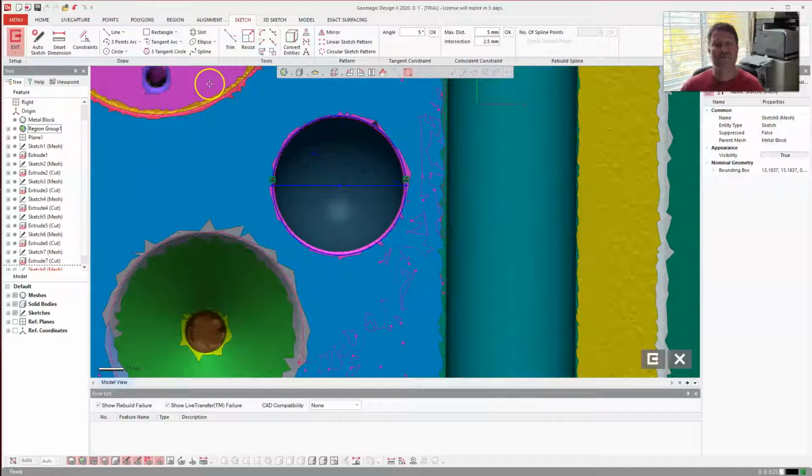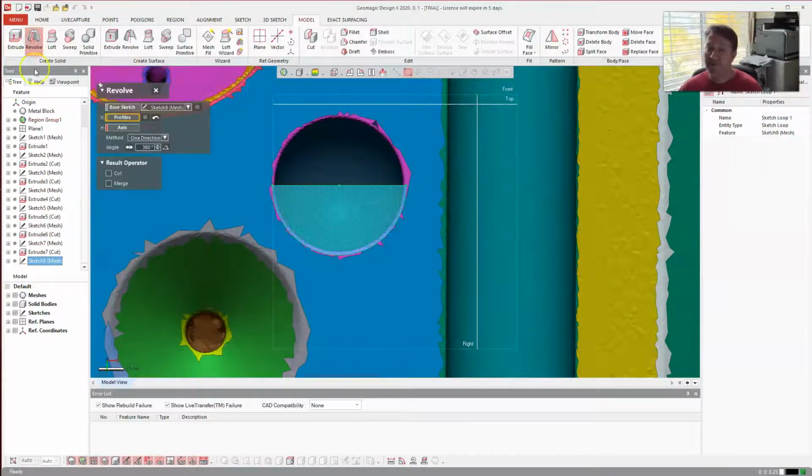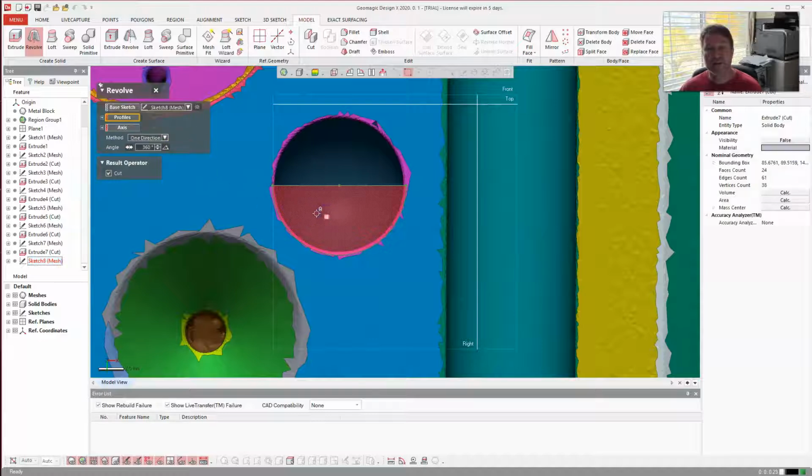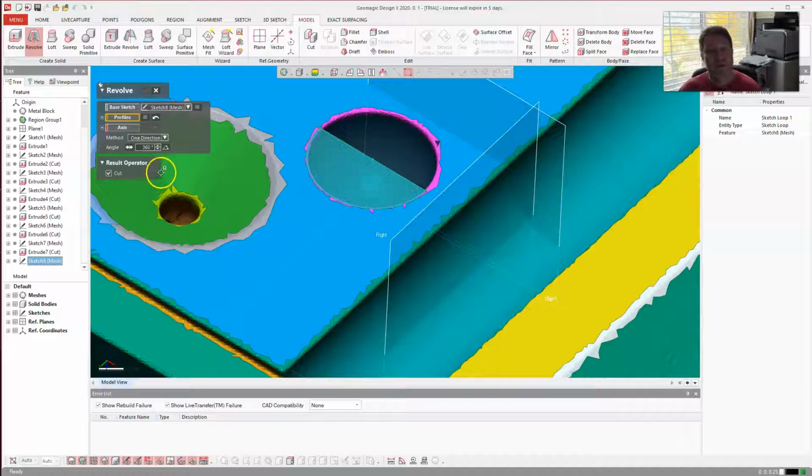Now, similar to SolidWorks, I'm going to trim out half. Now I've got literally a half circle. Good. Now let's exit. I've got this half circle. Now what we're going to do with that half circle, when you have it highlighted, let's do revolve. And revolve, just like in SolidWorks, I can do revolve or revolve cut. When you do revolve cut 360, you select the area you want.